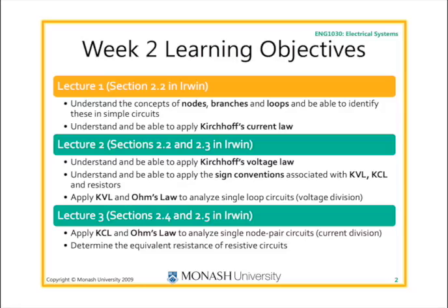Nearly everyone says that IX is 2 milliamps, so I probably don't need to go over it, but let's just double check. So let's suppose I'm interested in that node. I sum the currents entering that node to 0, so I must get IX plus 10 minus 5IX minus 2 equals 0.